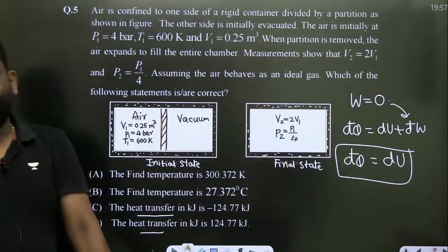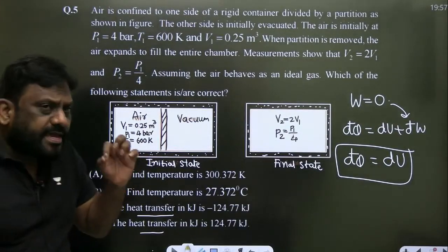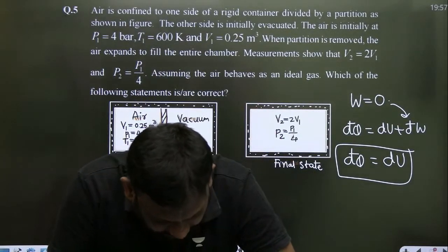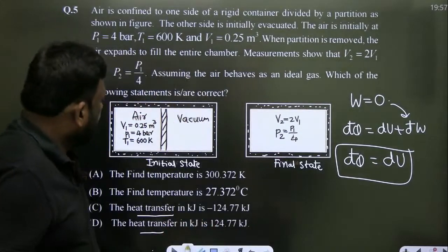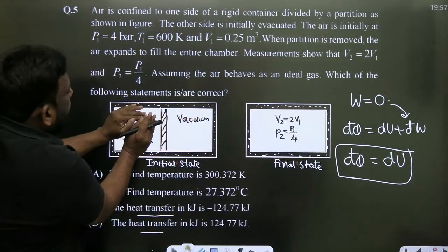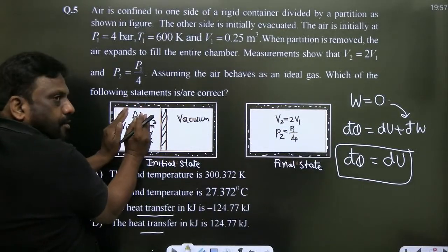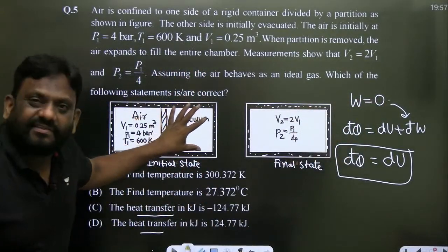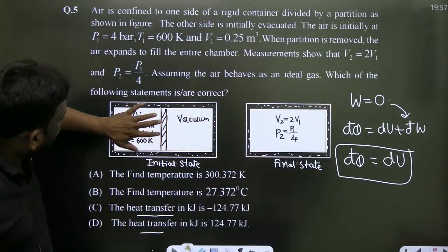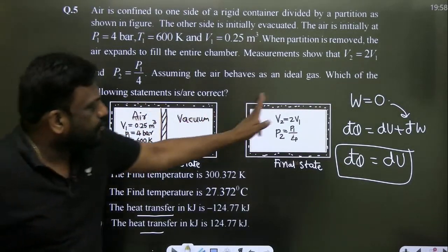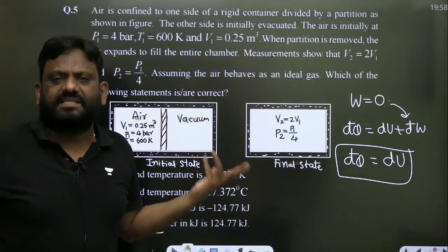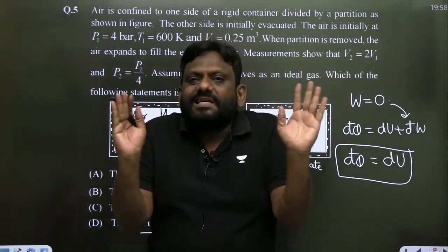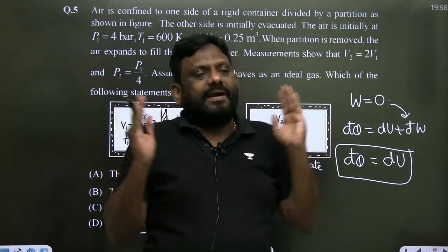But यहाँ पे careful रहो. ध्यान से सुनो. How can I find the final temperature? Let me explain very clearly. Originally, our air was occupying this small volume, and finally, the same mass of air is occupying total volume. So this side we have nothing, no material medium. Can I equate the mass of air under these conditions to the mass of air under this? Yes, mass conservation. So mass is neither added nor removed. The same mass is expanding.